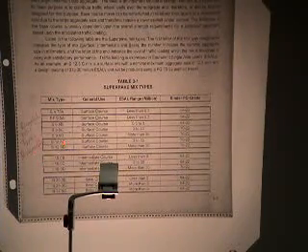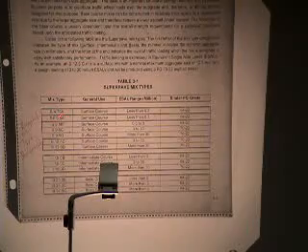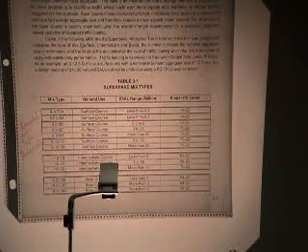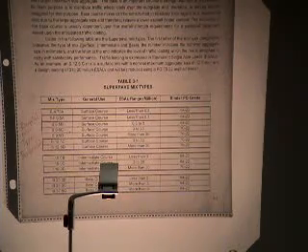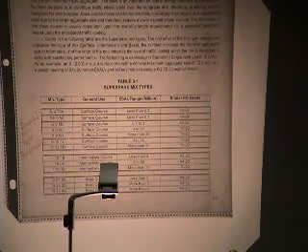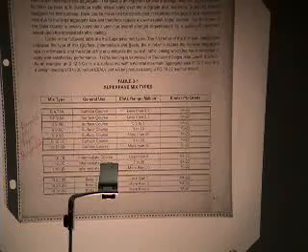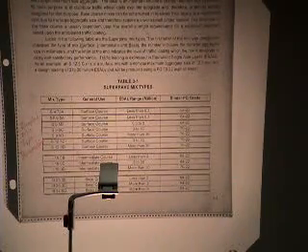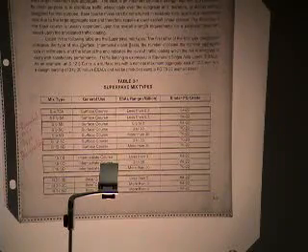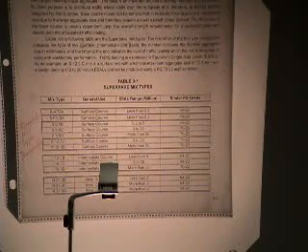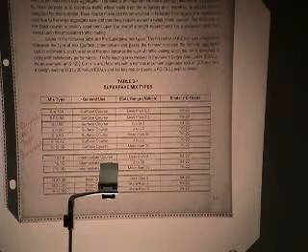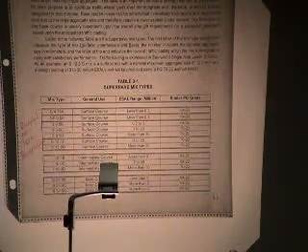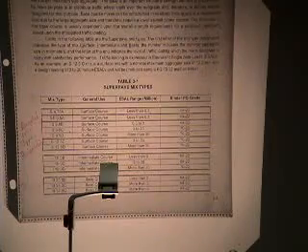And then the number is followed by a letter. That letter is related to this column right here. Related to the traffic and loading that pavement is going to be exposed to over that 20-year life. If you'll notice there, we have 4 levels, an A, B, C, or D level. A is the lowest level of traffic, D is the highest level of traffic.